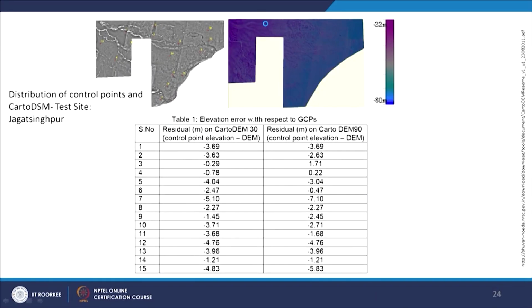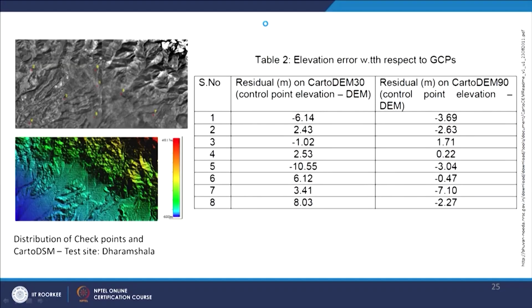Similarly, a lot of such work is being carried out to assess the quality of different elevation models, employing almost the same technique: you have to have true values, or assume true values which are independently collected, and then compare them with the values which have come from a digital elevation model against each cell. So against those corresponding test points, you get that value and assess it. Similarly, for SAR interferometry, again GCPs are used, and different residuals have been assessed.